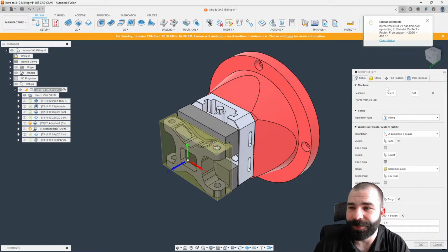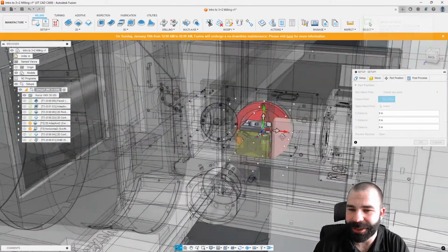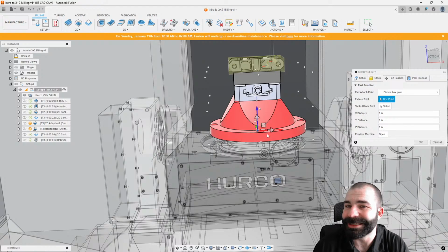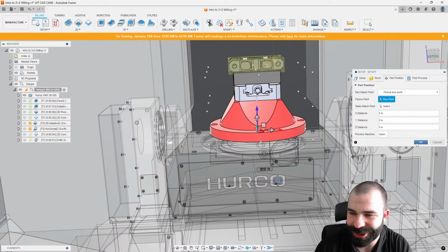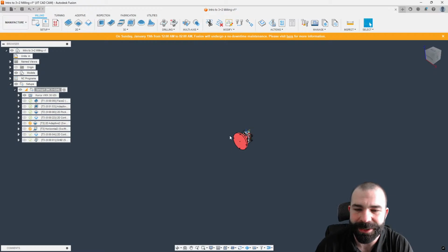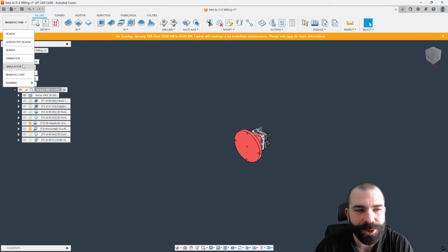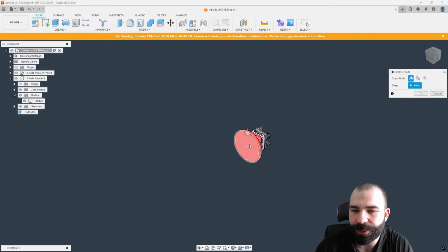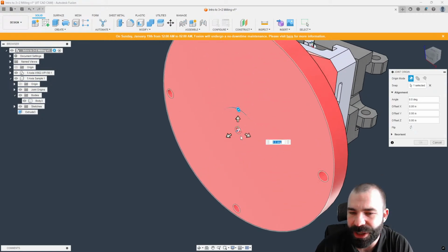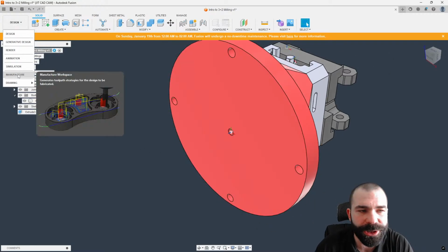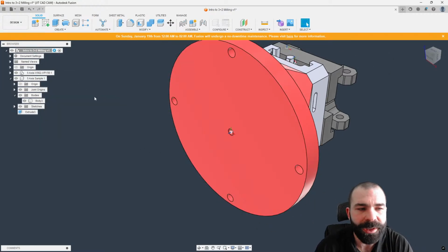Hopefully this is a full 5-axis machine. So those of you out there running a Hurco machine, you would be able to tell me right away. We lucked out because it is 100% a 5-axis machine. Now, if you haven't seen, another pro tip here is you can use joint origins in design for your fixture point. If I wanted to set a known fixture offset or a location to connect my fixture to my table, these joint origins can be very valuable on parts like this.